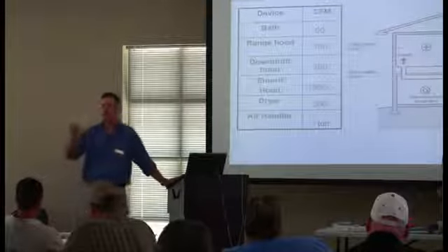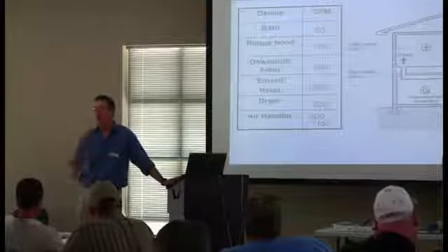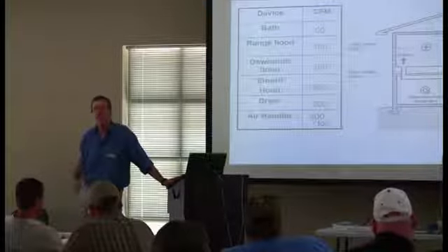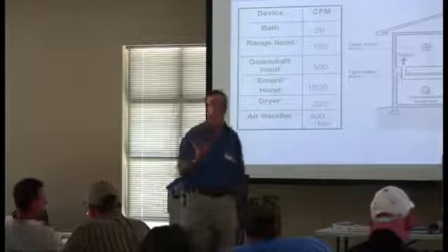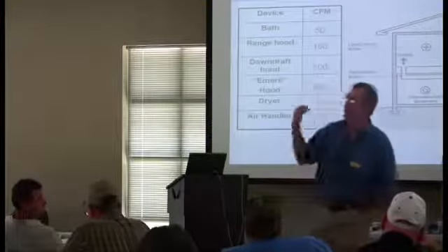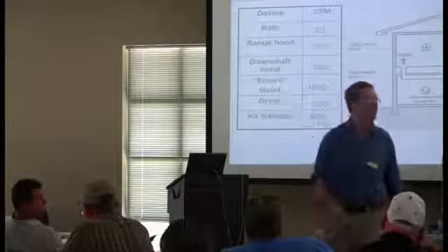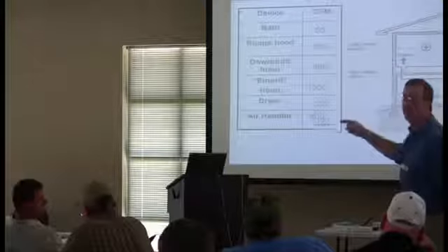Approximately how many CFM per ton of air conditioning? Maybe 400? That's a typical number you see kicked around. So it's not much. Even a fairly small air conditioner is like a 2.5 ton air conditioner. That's 2.5 tons, that's 1,000 CFM. 1,000 CFM being pulled out, but 1,000 CFM being put back in.